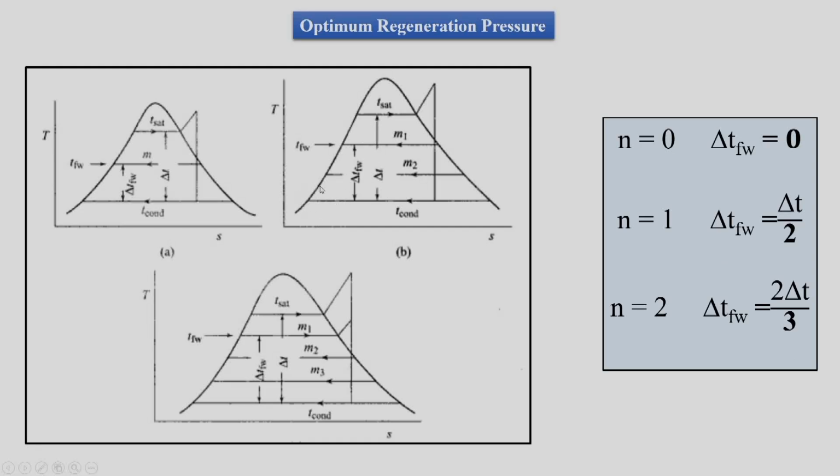So, we initially are here, at the entry to the pump. Now this is the total temperature rise which we are expecting. It is divided into 3 parts, 1, 2 and 3 parts. So we want to have maximum efficiency, so we have divided it into 3 parts. So we say as per this formula that 2/3 temperature rise means from here till here the temperature rise will be done by feed water heating and the rest of the temperature rise will be done by the economizer.